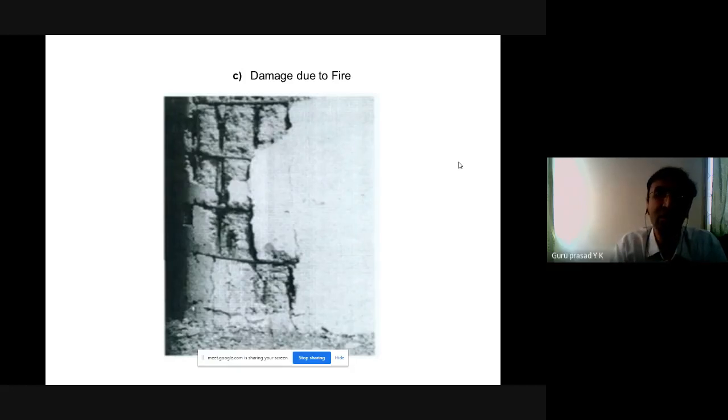And because of that, there would be separation of the mortar part of the concrete from the coarse aggregate, and also there would be loss of bond between the concrete and reinforcement, due to which there would be a large reduction in the strength of the concrete structural member, meaning the load carrying capacity of the member comes down.